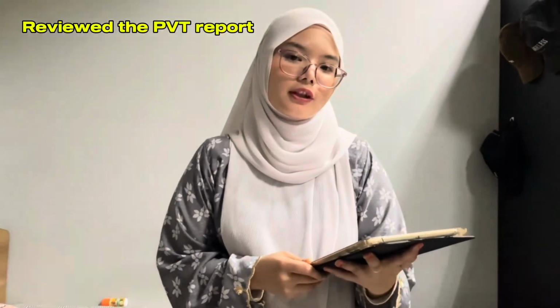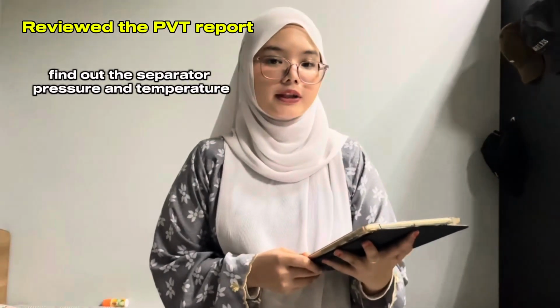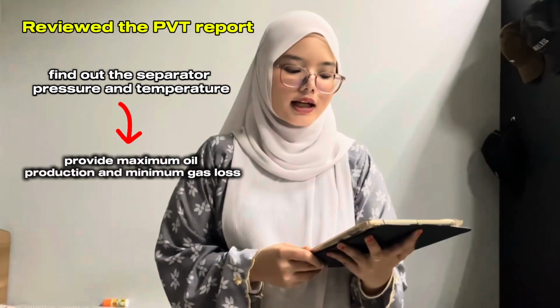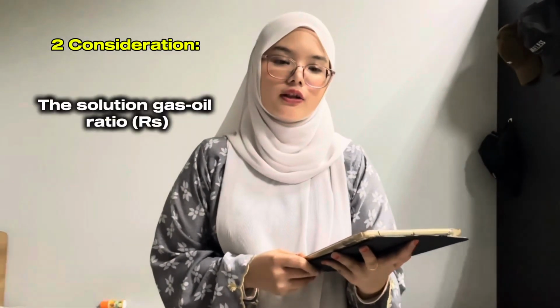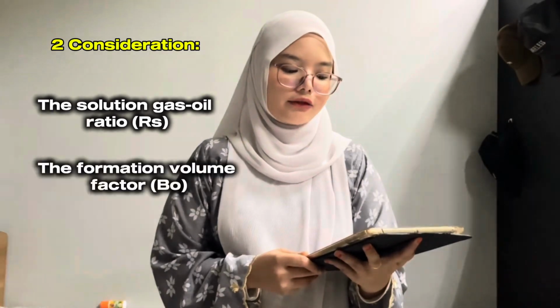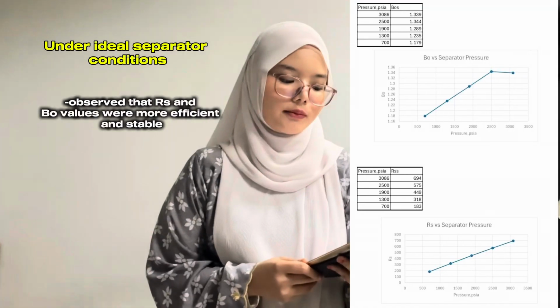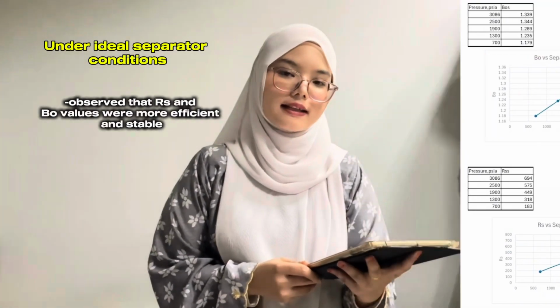Now, let us go ahead to calculating the optimum separator condition. We review the PVT report to find out the separator pressure and temperature that will provide maximum oil production and minimum gas loss. We have taken into consideration two things, the solution gas oil ratio and the formation volume factor. Under ideal separator condition, we observed that Rs and Bo values were more efficient and stable.